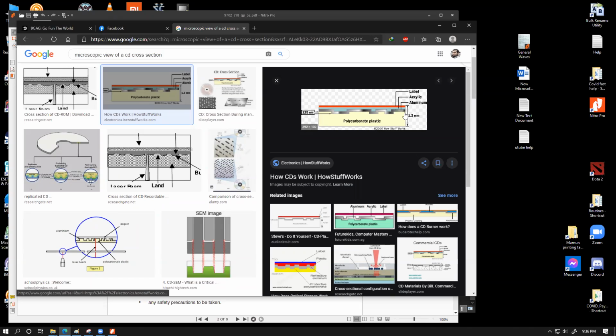And there is a certain aluminum layer that is lapped on that CD that looks like this. They have a certain gap size, and the thickness variation is 125 nanometer. This is very important. The thickness variation is 125 nanometer. Now what happens, because of this gap, whenever we send light, and this is polycarbonate, this is basically the structural